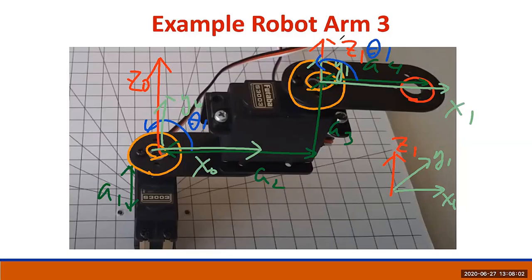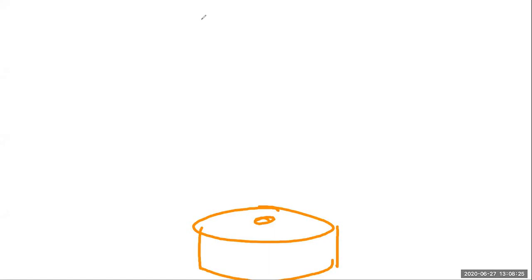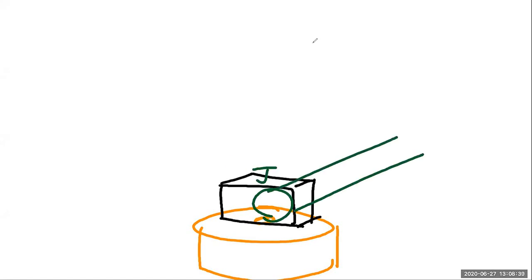Our xArm robot can also be modeled with a kinematic diagram. So let's look at it. Our robot actually has 6 different servos. That's servo 6, which is the base. On top of it, we build a solid block. And on this solid block, we have servo 5, which would be revolute joint number 1. Servo 6 is a rotator.